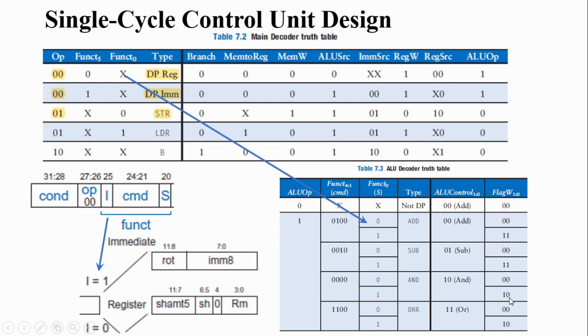So each bit is used for enabling two flags. Here the first bit is 1, that means two flags will be set. The other bit was 0, so the next two flags will not be reflected. If the S bit is 1, then only the flags will be reflected. You can see in each instruction, if the S bit is 0, flag bits will not be reflected.